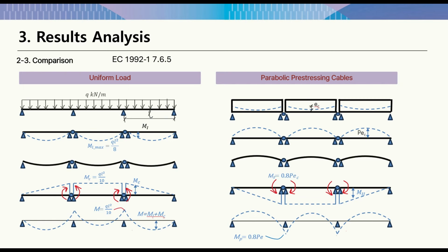The cables that lie below the neutral axis of the girder bend the girder upwards, requiring the secondary moments to act in the other direction to restore compatibility. Therefore, secondary moments reduce the moments at the support but increase the moment in the span. It should also be noted that secondary moments change the reactions at the supports. In a non-split statically indeterminate structure after prestressing, even though the sum of the vertical and horizontal components of prestressing is zero, additional support reactions arise.